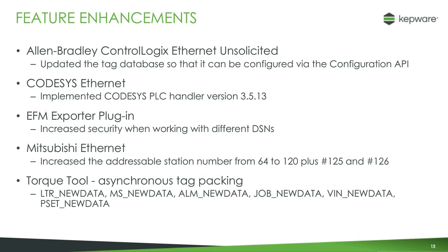We brought our CodeSys Ethernet driver up to date with their newest PLC handler version. So this will support all of the CodeSys devices that are out there, including the latest ones running the latest CodeSys runtime. The EFN exporter plugin, we've added some security work around different DSNs to make sure that you're getting the most benefits out of the secure DSN capabilities.